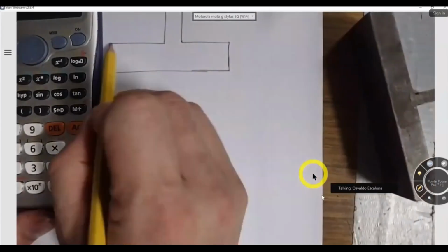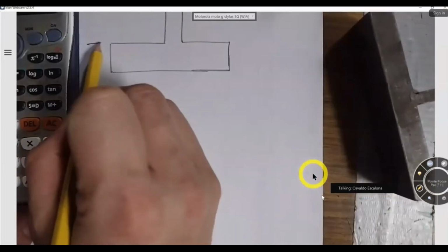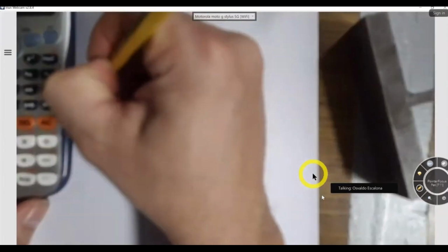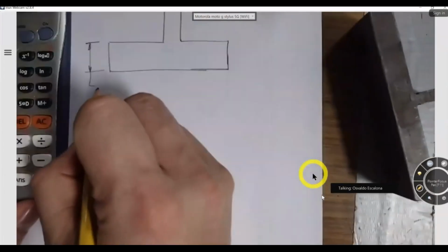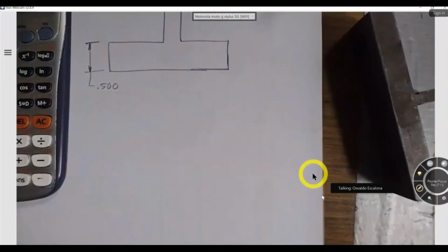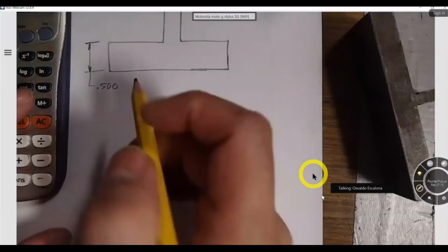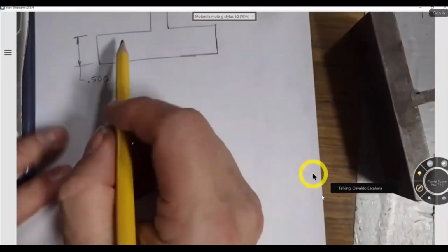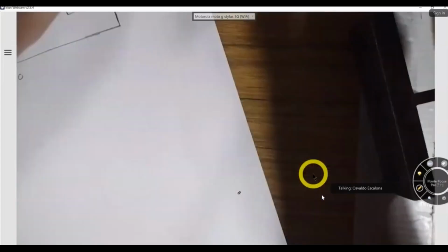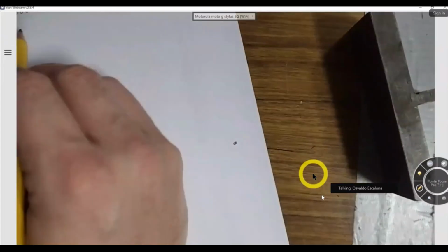Let's suppose I have a height and I tell it in my drawing, I model it, and I say, you know what, this has to be half an inch. I model it to half an inch, and then somebody needs to ensure that it meets my requirement. That little leeway, where my part will have a variance, is what we call a tolerance.